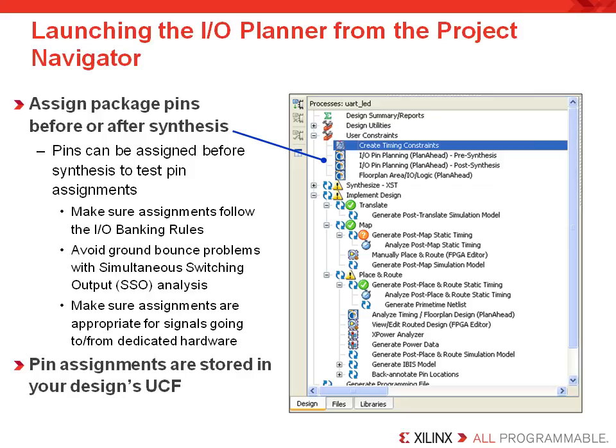The I/O Planner also makes certain that your pin assignments are appropriate for signals that are being routed to or from any of the dedicated hardware resources your design is using. All of this functionality is designed to help you avoid having to respin your board and resolve a pin layout problem later in the design flow.